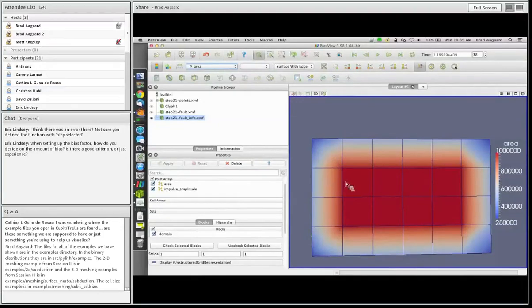It's documented in the manual that you can run it and it'll compute your magnitude, average slip, and so forth for any simulation. You do need to give it HDF5 files, and it'll look at your fault file at a particular time step, look at your material properties, and compute the statistics and information about how much slip, as well as what was the moment magnitude associated with that slip.